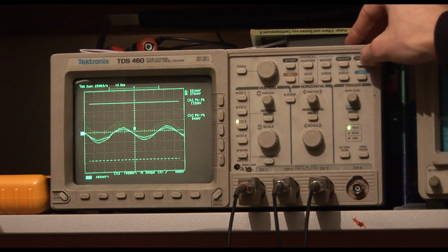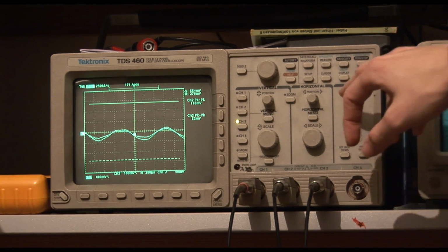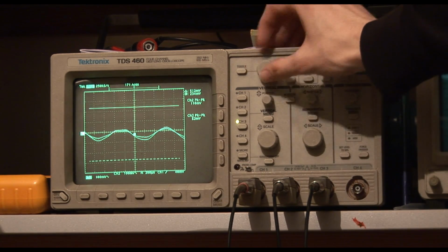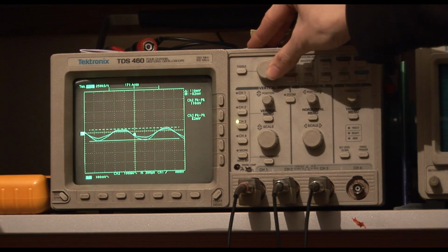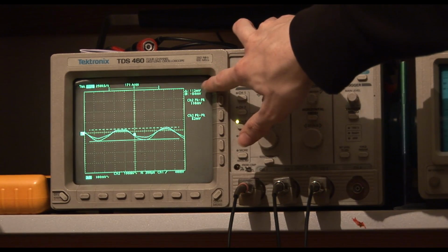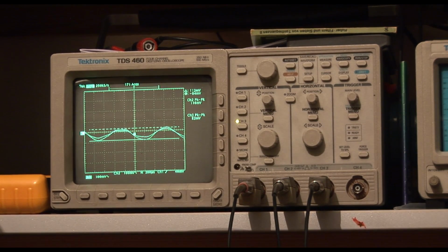Okay, and now it's very hard to measure exactly with this automatic measurement. So what I will do now is turn off the automatic measurement, or stop the thing, and then I will measure it manually with the cursors. And the delta is about 110 millivolts or so. So the common mode output voltage is now 0.112 volts, and now we can compute the common mode gain.